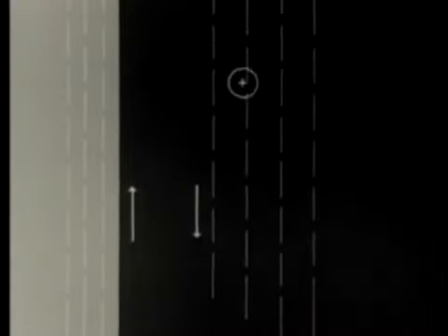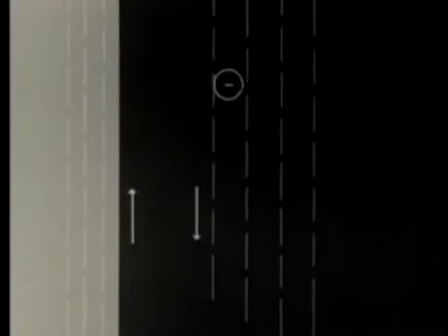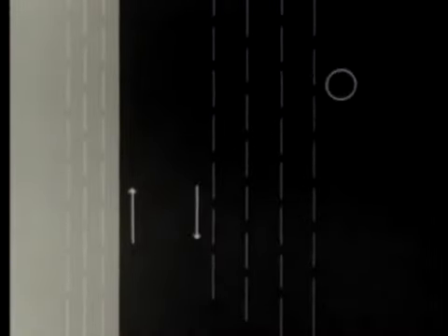This represents a piece of wire which we will move through the lines of force created by a permanent magnet. When a wire is moved through lines of force, a potential is induced in the wire which alternates as the wire is moved in or out. We can increase this potential by speeding the motion of the wire through the flux field created by the magnet.